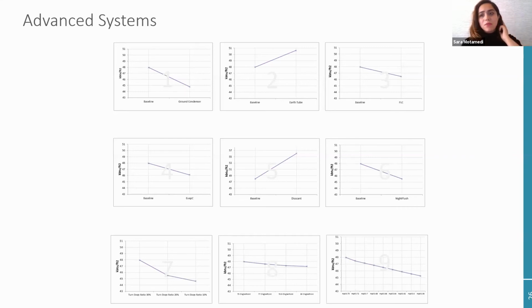The other thing I want to mention is that it's maybe a little bit complicated when it comes to the HVAC system. On the envelope part, on the equipment or lighting, architects can definitely get in, but when it comes to the HVAC system and what numbers you want to put in, it does matter to understand, and it does matter to maybe have some consultant on the board when you are running the simulation.